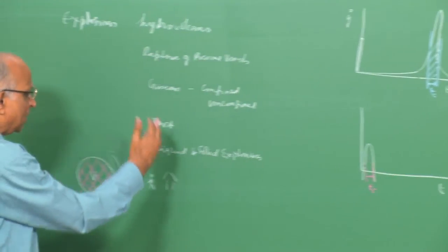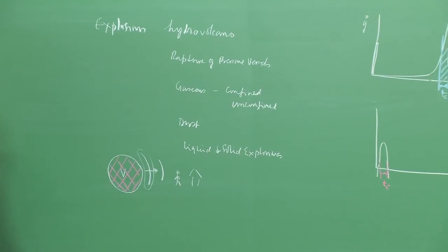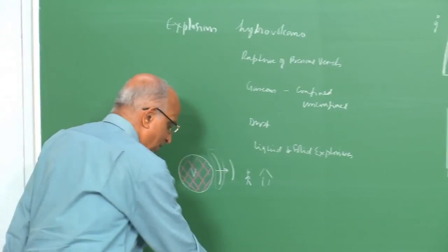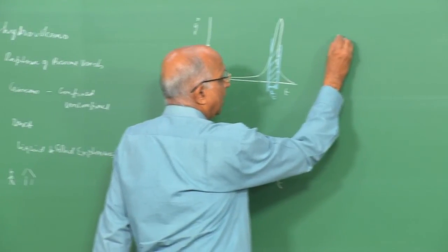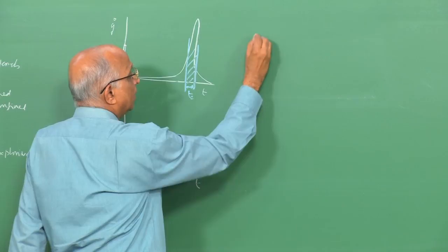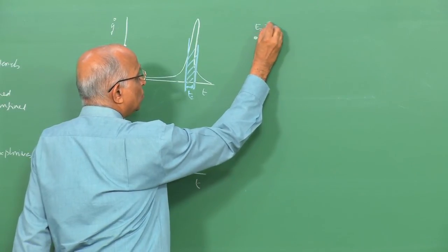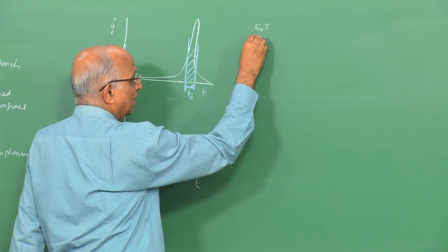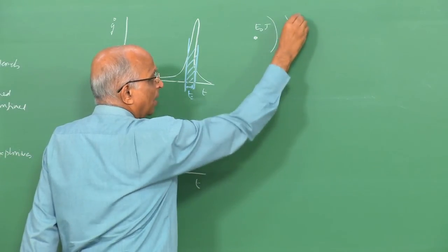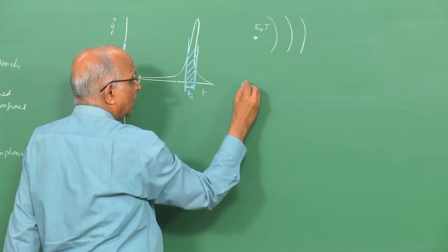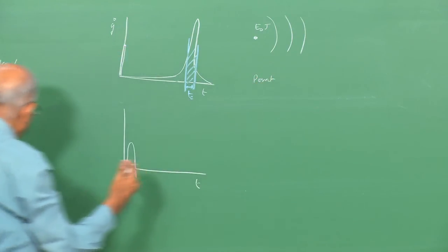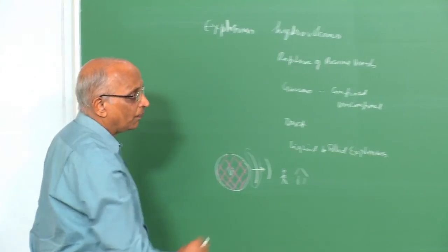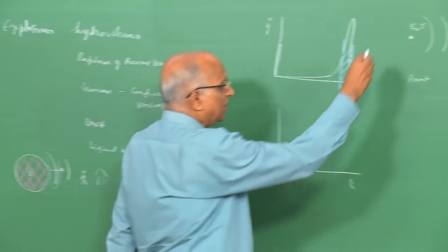But when we talked in terms of, let's say, blast waves, we modeled it. What were the assumptions we made? We made an assumption that at a particular point, some energy E0 joules is impulsively released, and this drives the blast wave. In other words, we are talking of energy which is released at a point, but in practice, what is it we find? Energy is released in a given volume, point 1. Point 2, it is impulsively released.